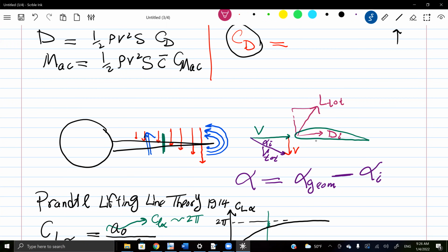This component is what you call the induced drag. And unfortunately, it's so large, it's actually the same order of magnitude as the skin friction drag. So you simply doubled your drag, and it's unavoidable, it's inevitable. Why are we always obsessed about induced drag? Because it's drag due to lift, and the lift is inevitably needed, so the induced drag is unavoidable. So you're unavoidably doubling your drag force. This is why it's a big thing, and we're always obsessed in wing design with minimum induced drag.